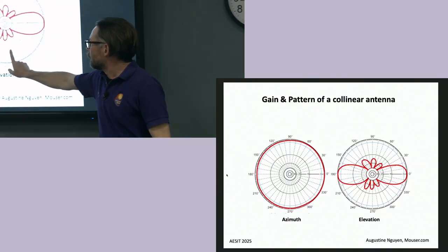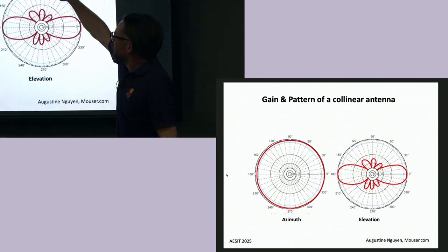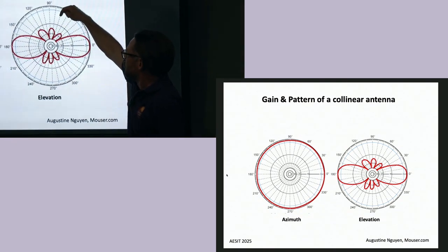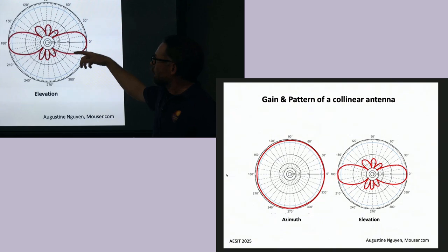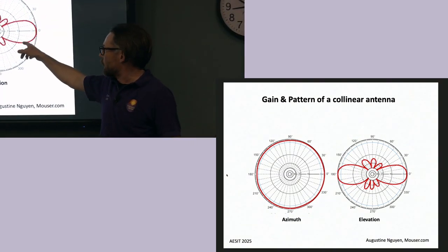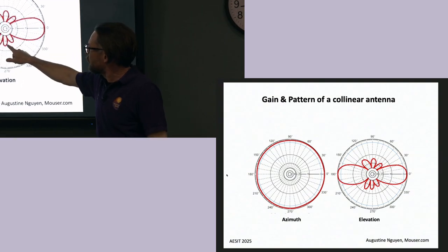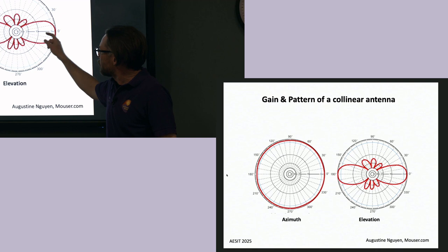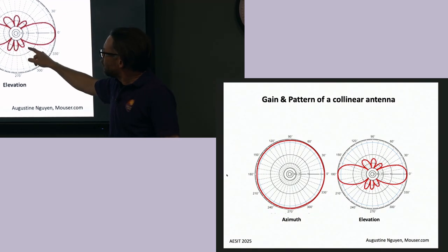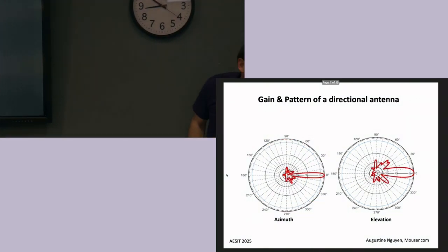Again, there aren't any worms walking around with a walkie-talkie. Probably people in airplanes we're not trying to talk to. We don't care about them. If this is like a repeater site, we're sending signal out to the horizon. We want to be catching people walking around on the ground or in their car. So we care about these main lobes. We still get some smaller side lobes here. They're a little bit unavoidable. Same thing with the Yagi.